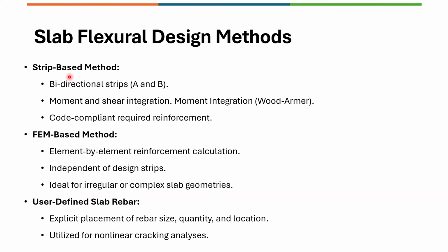A strip based method should be used if you want to perform the detailing action. For FEM based, detailing will not be performed. And there is an option to input user-defined slab rebars within the section, within the members. That is to utilize in the nonlinear cracking analysis.